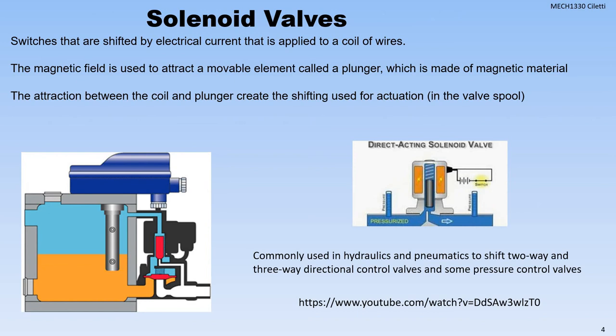Heavy use with solenoids. Remember solenoids from electrical class? We're taking a coil of wire and putting a current through it. That current induces a magnetic field, and we use that magnetic field to open and close the plungers in our directional control valves. We give it our electrical signal from the PLC. If it's a 1, we're going to open the plunger and allow air to flow through that way. Very common. We did a lot of this in electrical class, and some labs. Those of you that haven't taken electrical yet, it's okay. I'll show you those on the 870 trainer and some of the other trainers that we're going to use.